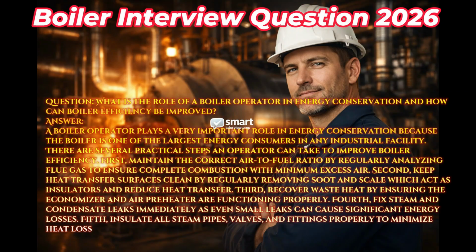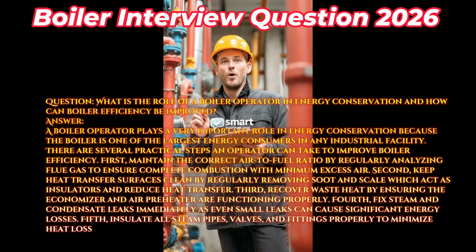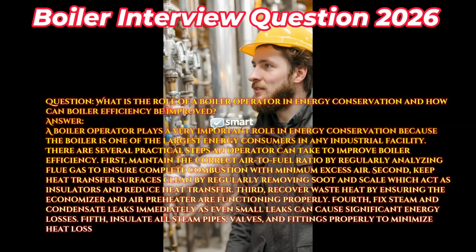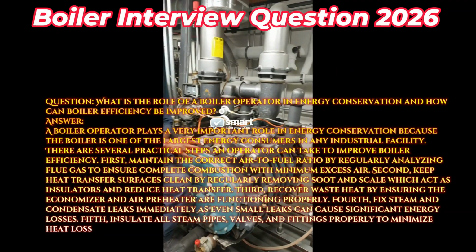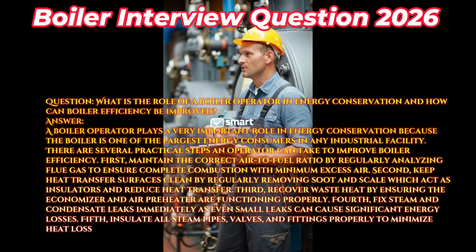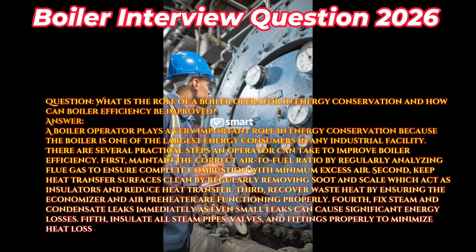Question. What is the role of a boiler operator in energy conservation, and how can boiler efficiency be improved? Answer. A boiler operator plays a very important role in energy conservation because the boiler is one of the largest energy consumers in any industrial facility. There are several practical steps an operator can take to improve boiler efficiency. First, maintain the correct air-to-fuel ratio by regularly analyzing flue gas to ensure complete combustion with minimum excess air.